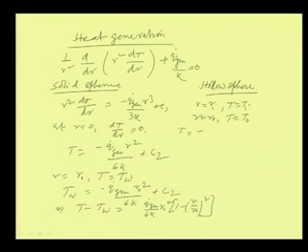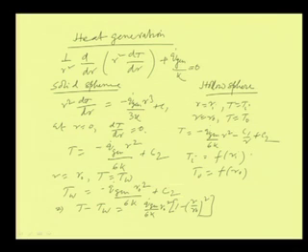that T is equal to minus q dot gen by 6k into r square minus C1 by r plus C2, and then from there we can find out T_i as a function of r_i, and T_o as a function of r_o, just by putting the values of r is equal to r_i, r is equal to r_o. We put the value, we will find out the values of T_i and T_o, and then we will find out different expressions.